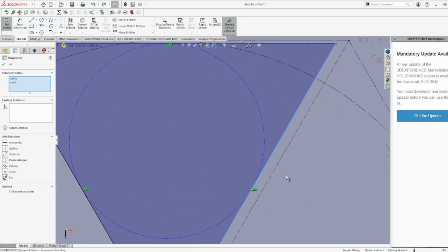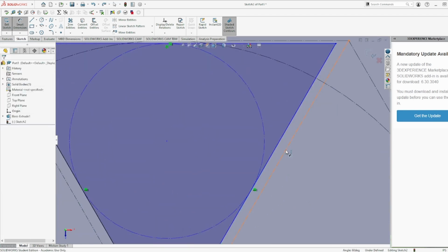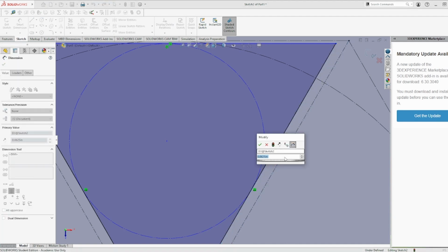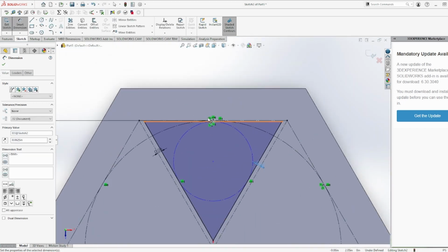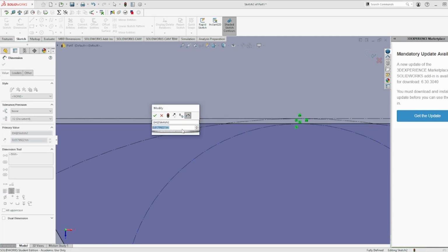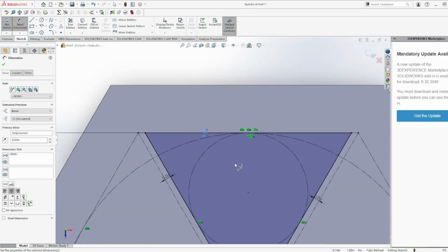Edit. Okay, good. Smart dimensions again, these two. So this should be 0.0256 inch. Yep, that's good. And finally, the back of these two has to match. Click on this, click on that. It's changed this to 0 inch, which means that back will go against that, which is good.